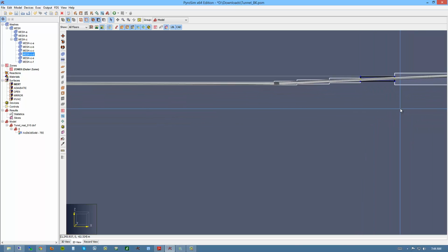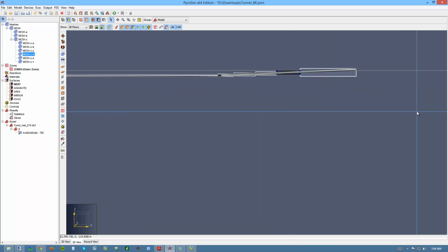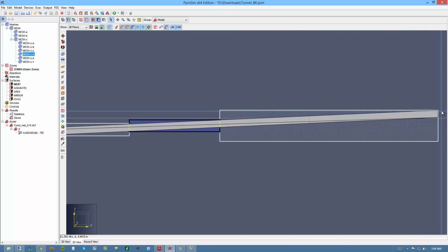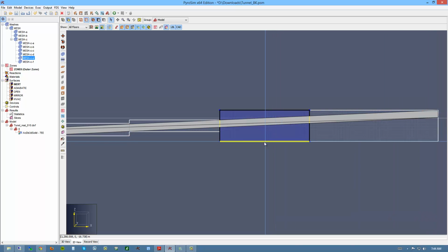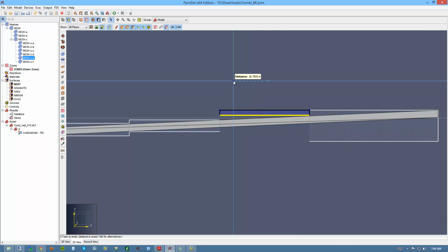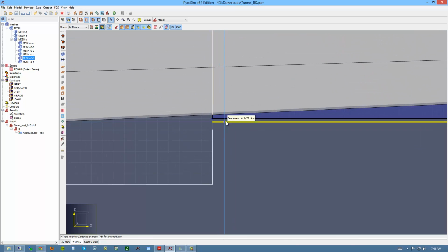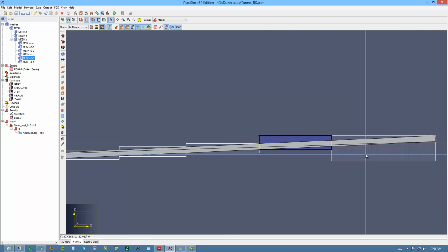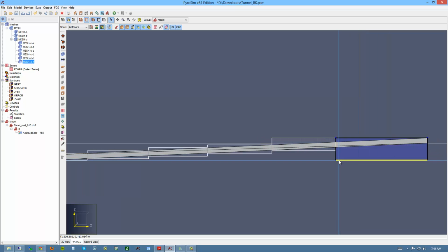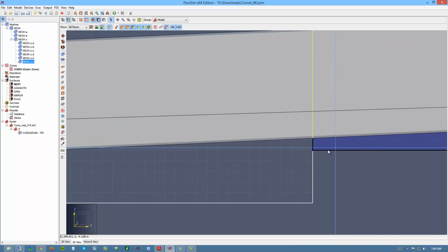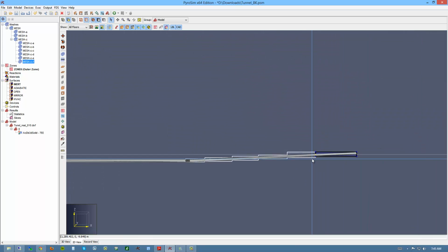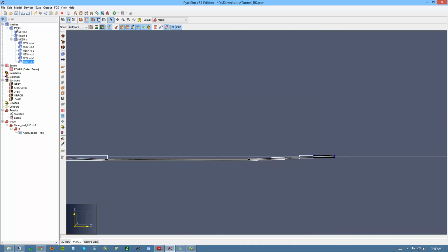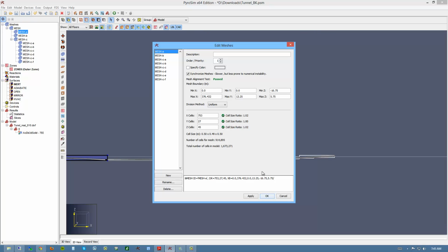So we'll do this one end of the tunnel and see what the reduction is. So this is already at the top, but this bottom can pull up. So we'll grab this, and we may be able to get it. Yeah, we can get another cell there. And then the last one. And that's, I think, yeah, maybe we can go up one more. Okay, so there's this end of the tunnel. Now we'll take a look at our meshes. We're down to 1.6 million.